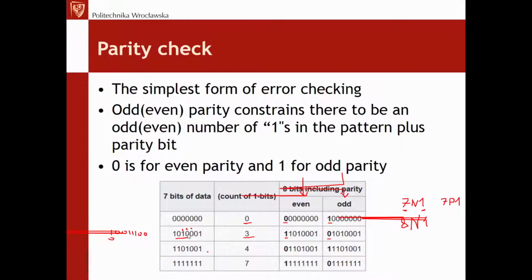From a practical point of view, it's more time consuming to make the comparison. You can see here that this comparison does seem simple, because you just take a look and see, okay, there are 3 ones, there are 4 ones and 7 ones. But remember that from the microcontroller's point of view, we have to analyze the input data bit by bit, check how many there are and count those bits. So we have to check each data bit of information.